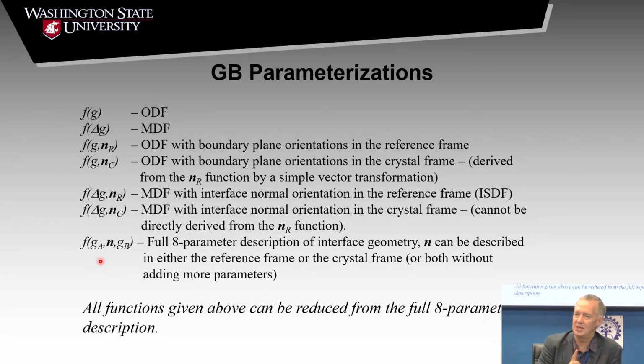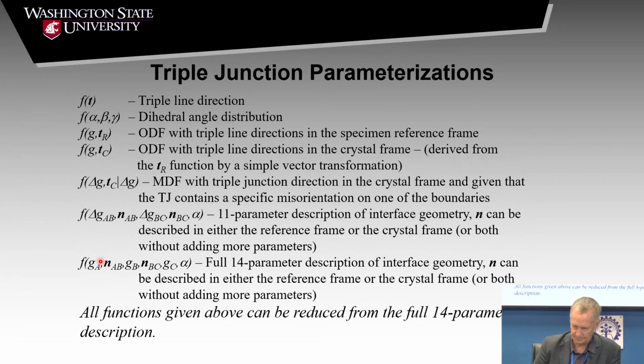So then we would need that additional external reference frame. So for the grain boundary, if we're talking about deformation, you almost always have to use 8 parameters, which makes it a much bigger space. So we usually ignore that, think about energetics of the boundary, how they form, use our 5 parameters, okay?